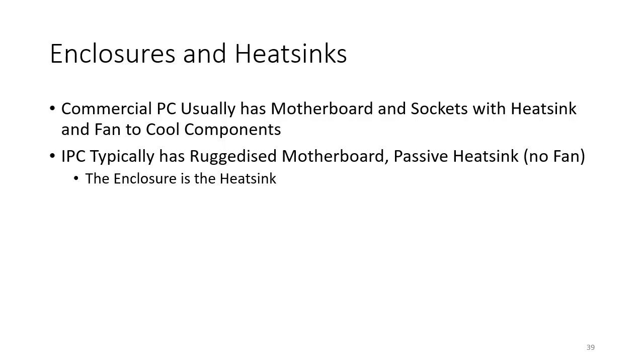And if you're really into cooling, you might have multiple fans. You might even be looking at liquid cooling, and you would take that decision based on how much noise you can cope with, because fans can be noisy. The reliability, of course, because fans can be unreliable. Typical MTBF on the commercial fan is only 3 years. So if you're using your system regularly, you might need to replace fans. And also cost, of course. The more fans you've got, the more it costs. And size. Fans do take up space.